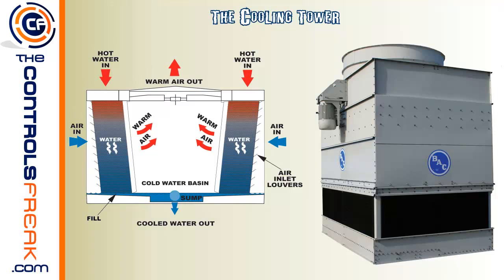So the cooling tower's purpose is, as you remember, the condenser side of that centrifugal chiller is going to have hot water coming out of it. And what we need to do is cool down that water to help keep the chiller cool on that side of the refrigeration cycle.